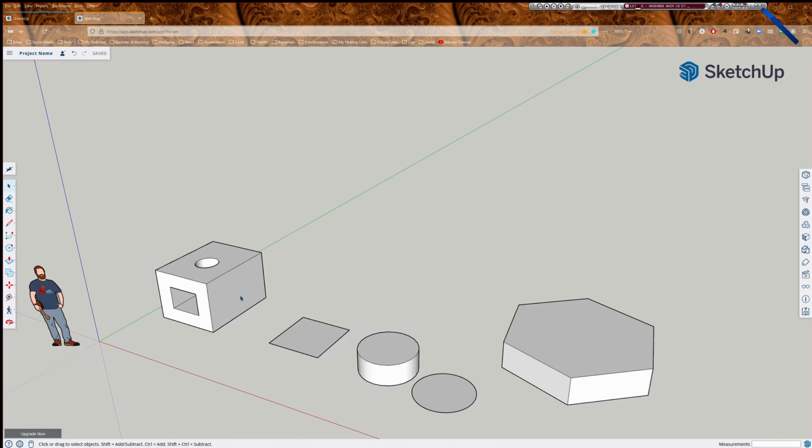When I say raw geometry, this is the raw shape. So when I just click on one of these faces, it selects just that face, then that raw geometry. And why this is important is if I was to take this other square here and turn that into something. Right. Now if I take this and I triple click it, it selects everything that's connected. And we'll move it. So we're going to use that M again. And I'm going to put it right on the face here somewhere.